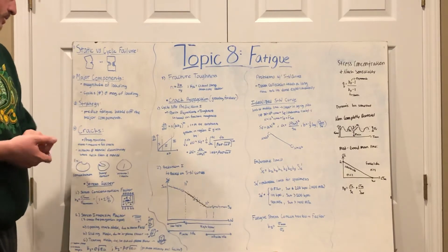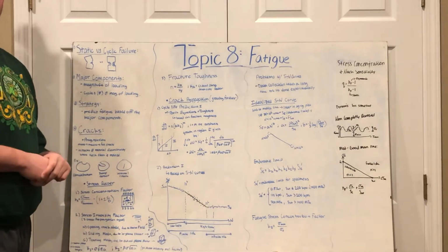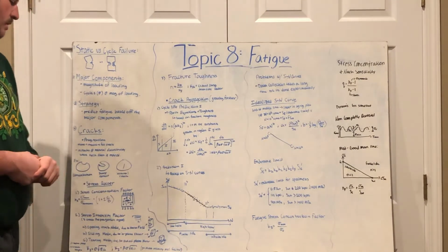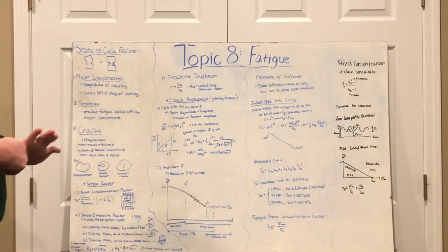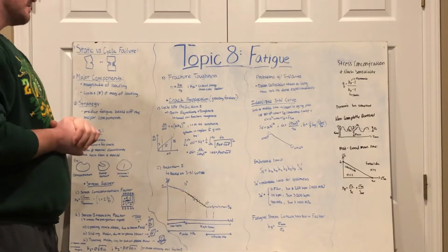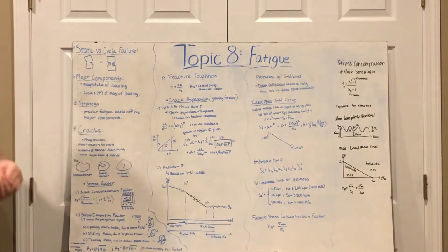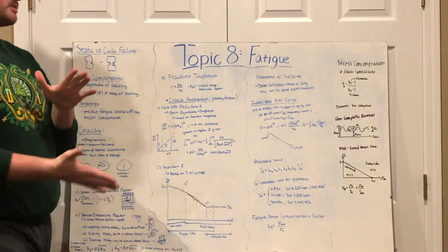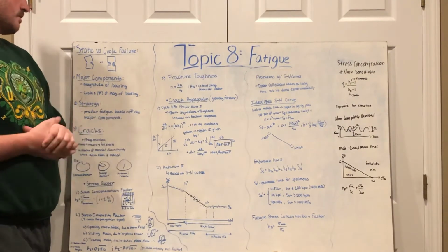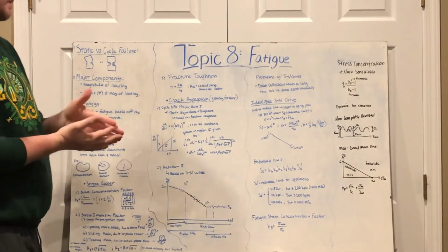There's a secondary one where you have to worry about a stress intensity factor given by beta, and it's simply the same equation stated before, multiplied by the beta factor, the stress intensity modification factor. And the third is fracture toughness, given here as n equals K_IC over K_I. K_IC is the critical stress intensity factor, so at the maximum stress, that's where it's going to be most critical. Now, the other component of cracks to think about is crack propagation, or how the crack is growing further or faster.